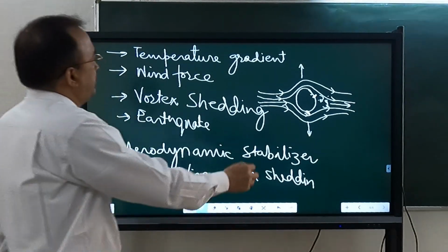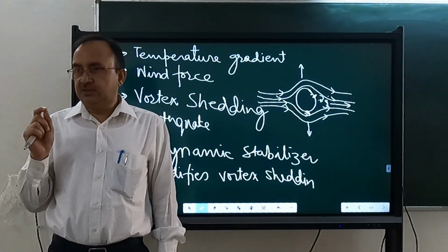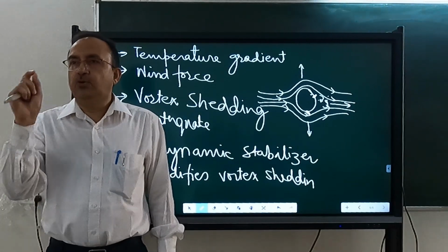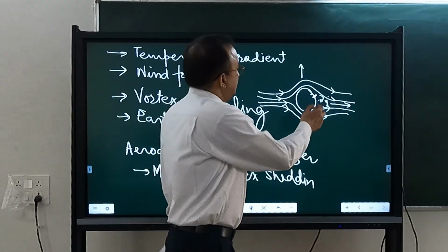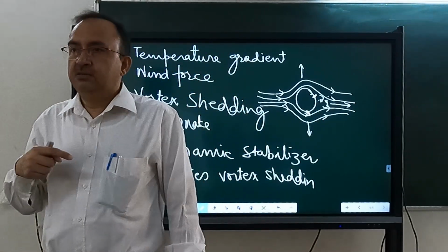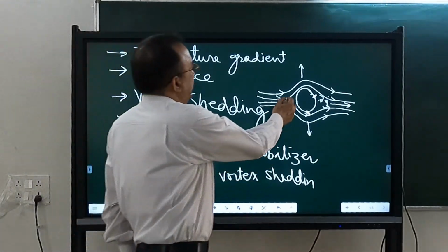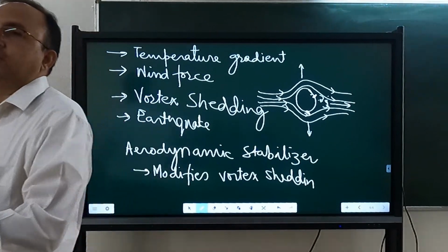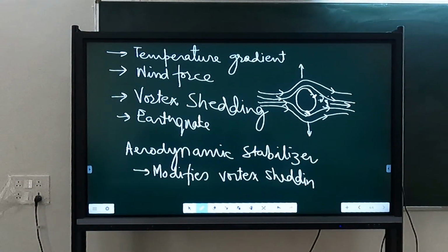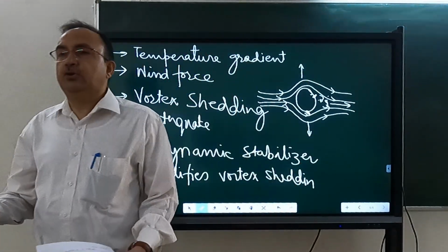So these are not very large elements, small elements only, which just disturb the flow of air. When the flow of air is disturbed, then turbulence will occur. And when turbulence occurs, then the area behind this is no more a shadow zone. Here also wind will come. And then this eddy current formation will not take place. Regarding asymmetry, so that you can take into account.